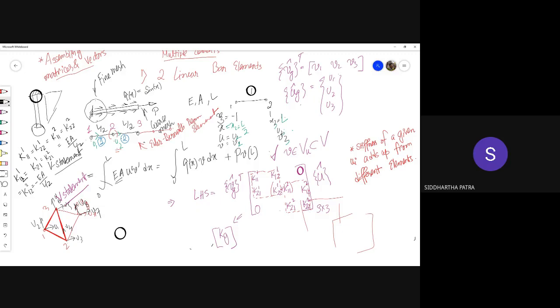And similarly, the V matrix would also be V1 to V8. And then I need to note down the element stiffness matrix for one of the elements. And then instead of numbering them as 1, 2, and 3, I would number them with global numbers. For example, for the second element, the numbering should be with degrees of freedom 3, 4, 5, 6, 7, 8.